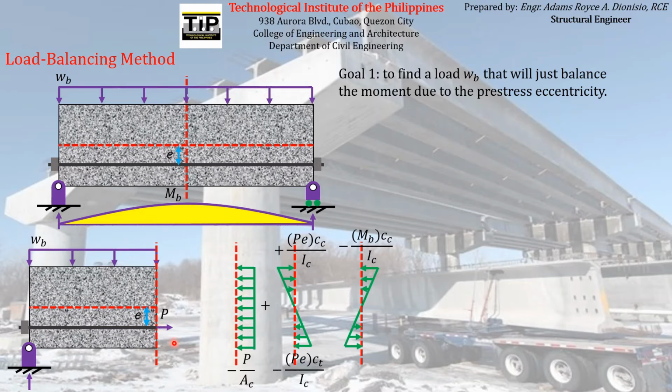So if that is a counterclockwise moment, the resultant couple of the several forces must be equal to that moment with the same direction. So with that, to be consistent on the direction of the bending moment produced by the balance load, the flexural stresses on the upper portion of the neutral axis must point towards the concrete element, which will induce what we call compressive stresses.